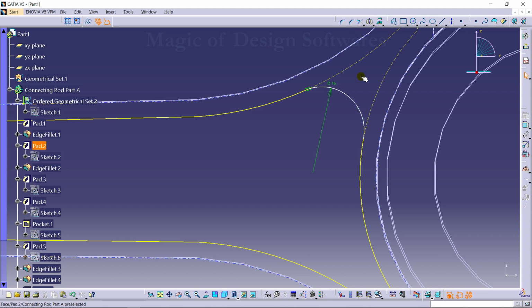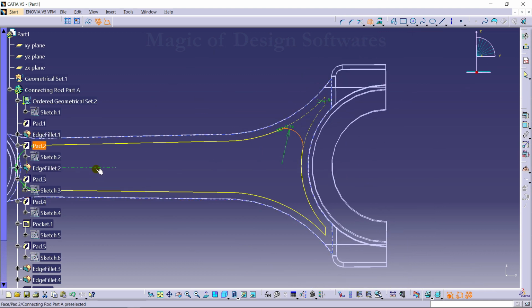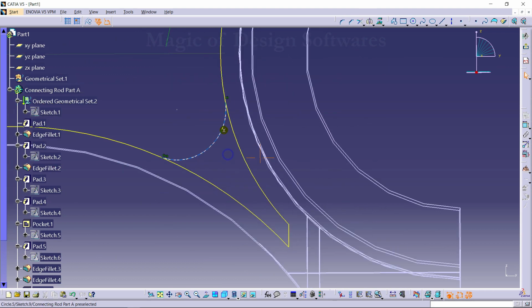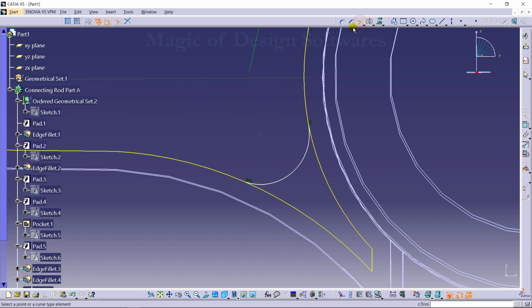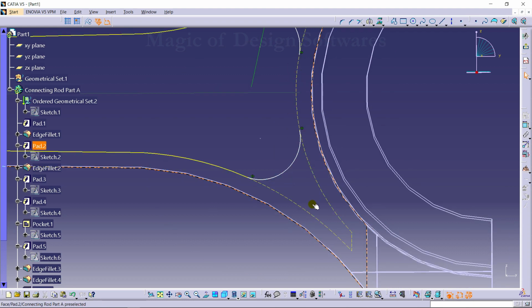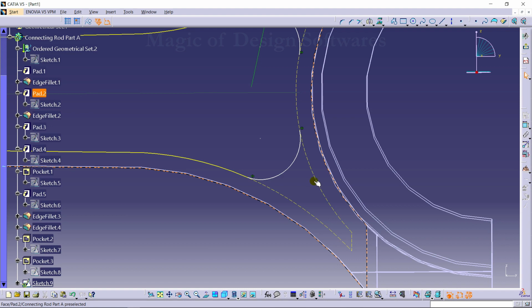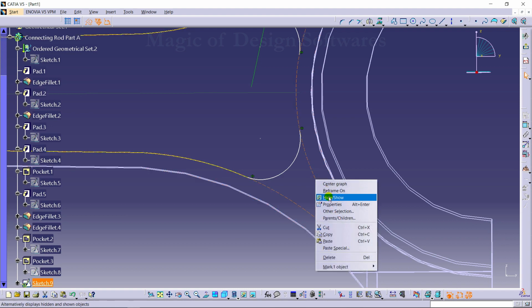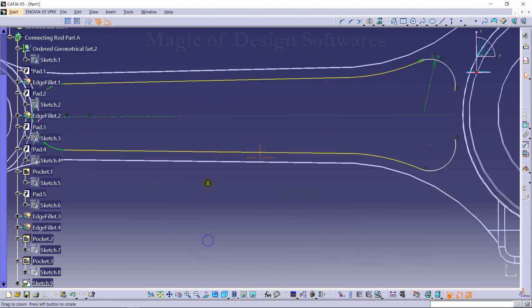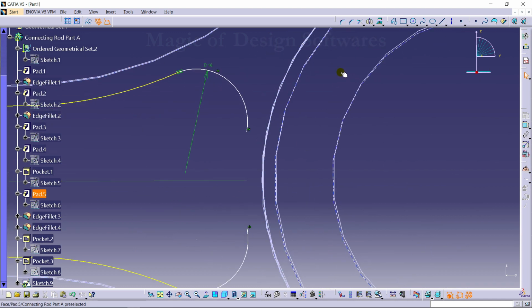Okay, now just selecting this, making it a mirror with the center line, and now going again for a command called trim. So I'll select this profile, coming back to the circle. You can see this portion is converted into a construction mode line. Okay, so for now I'm just selecting this one and hiding this. Okay, and selecting 3-point arc.